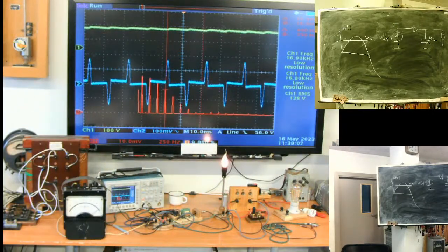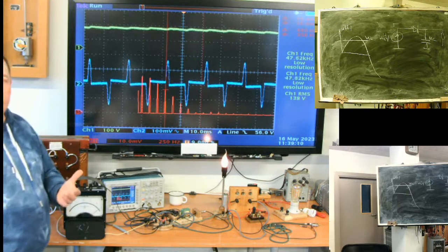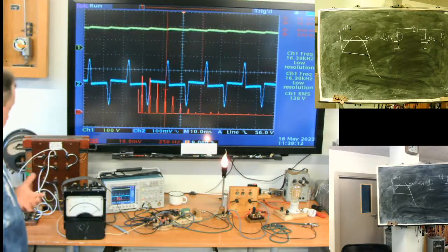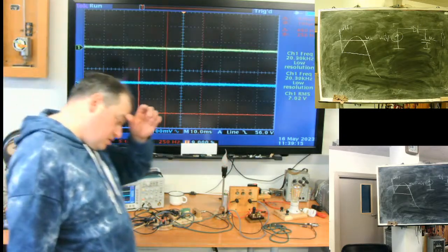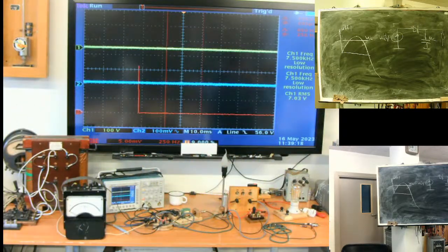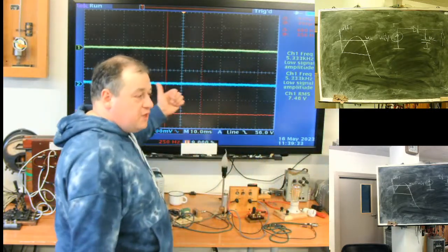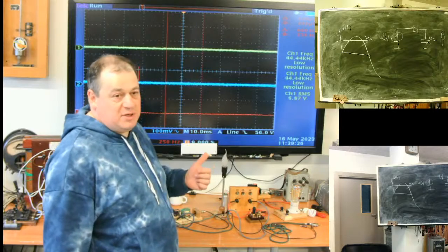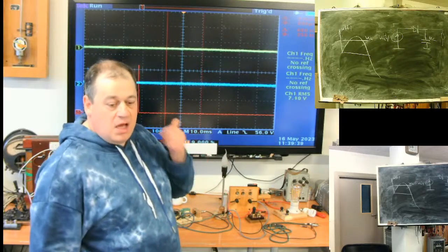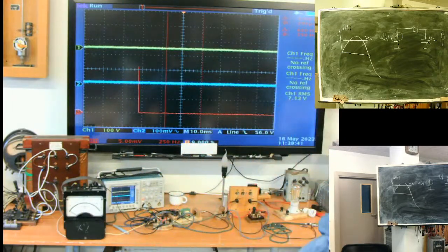In the worst case, you will have to pay for an active filter to suppress the fifth harmonic, plus a set of capacitors. This will slow down your machine. This will make you pay. I showed them in opposite direction, but you saw both. The neutral wire of modern networks is a path for the third and so on harmonics to circulate.